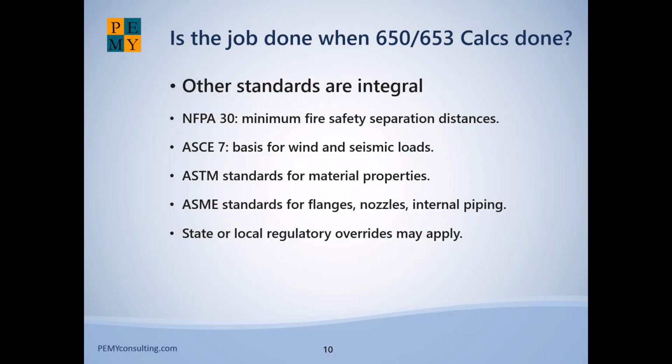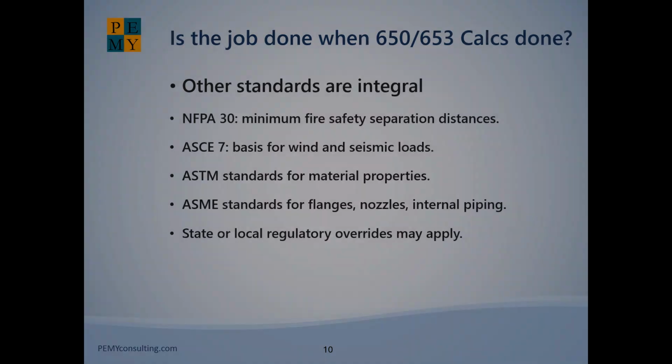Completing the API 650 or 653 calculations does not mean that the job is finished. Tank design and evaluation sit at the intersection of multiple standards: fire protection, wind and seismic loading, materials, and piping, plus any state or local regulatory requirements.